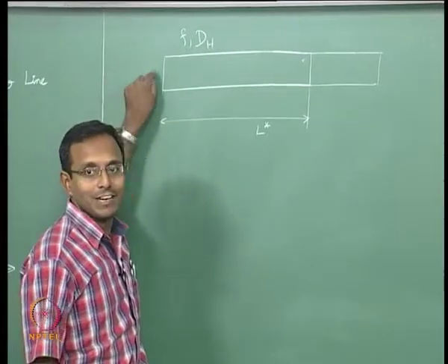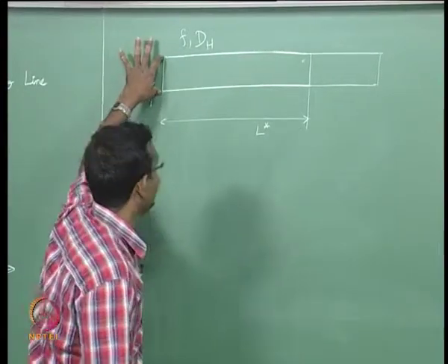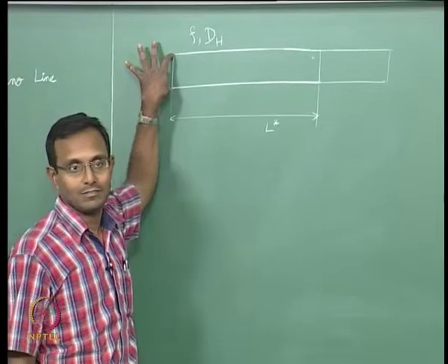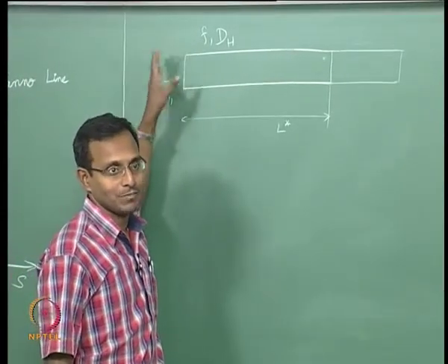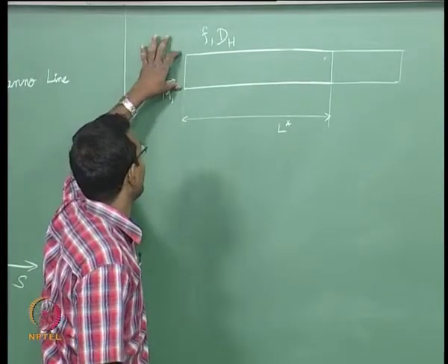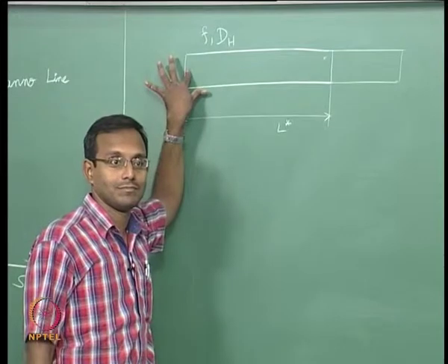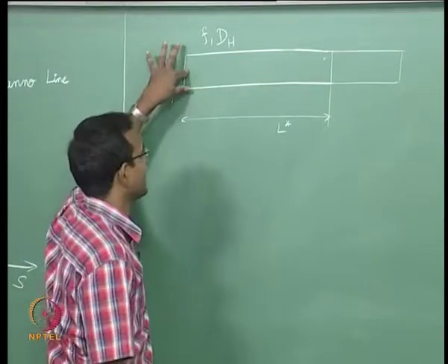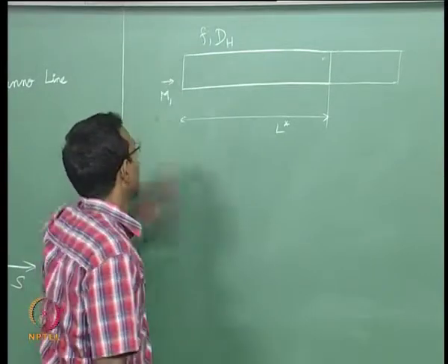It will go and change the inlet Mach number. So what will happen overall? My flow velocity at the inlet is going to be lesser, okay. Density also will be adjusted accordingly based on the Mach number, okay. And finally I am going to have a mass flow rate that is lesser, okay. A mass flow rate that is lesser, what will be the final situation, okay.